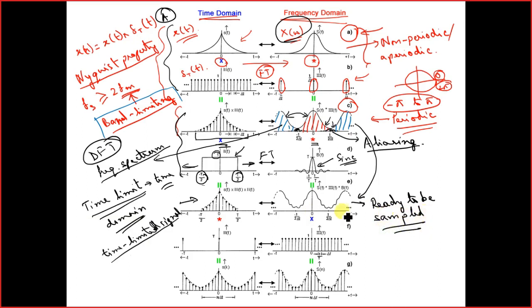Okay. Same thing, we need to multiply it with an impulse train, but this time we have to multiply in the frequency domain. So delta f of omega, whatever you can use. Previously I think we have used x of omega, so here also we can use omega. So delta f of omega. If you perform multiplication over here, it becomes convolution in the time domain, and when you multiply it, you can see we are getting a discrete frequency spectrum.